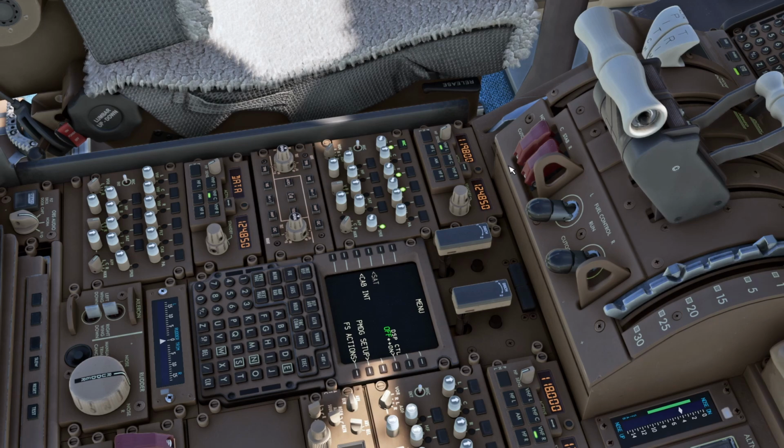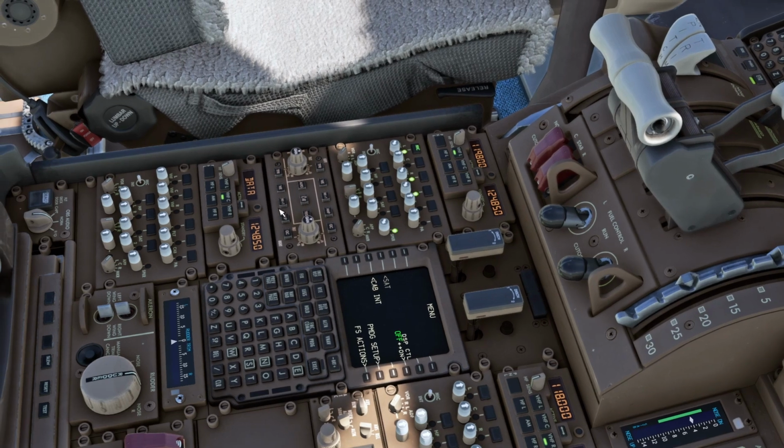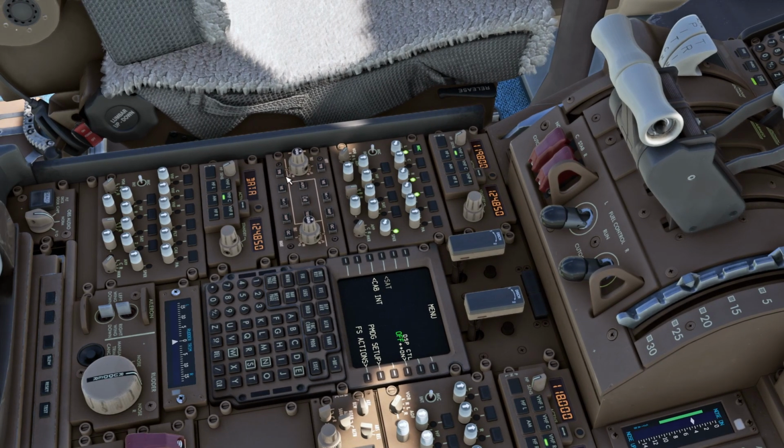Now we'll go through the pedestal right here. You can set the left tuning panel. I'm not gonna go into much detail, but again, if you're flying on VATSIM, make sure that you have your microphone selected to the correct VHF radio, in this case VHF left, and the corresponding volume knob is on as well. So this is to receive. If the microphone is selected, it should receive also automatically. You cannot control the volume, unfortunately, but in real life you would of course be able to. So make sure you give that a good review. The weather radar panel, we do not really touch that at this stage. You can touch that in flight.